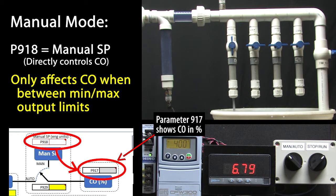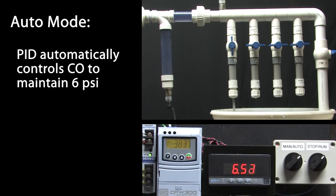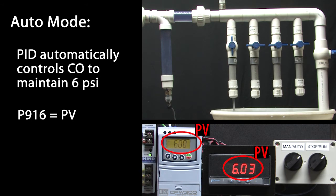So could we have set up PID first, and then generated our curves using this manual mode where we manually control the output of the drive? Yep. Just widen up the min and the max drive frequencies before you start, and change them to the values you need before running PID. Great, manual mode works. Let's flip over to having PID control the output to automatically maintain 6 psi. And sure enough, with one valve open, the system settles out right at 6 psi. Cool. And remember, you can also see the process variable in parameter 916.